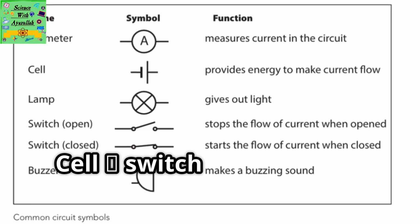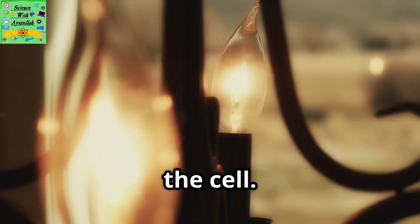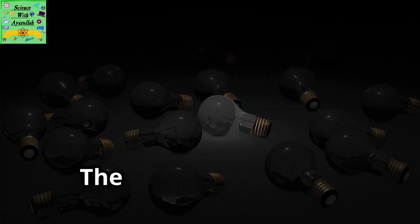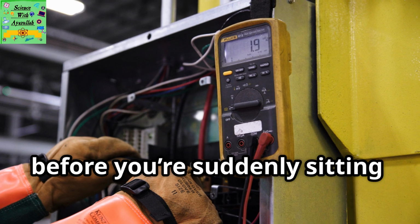Circuit 2, a lamp you can measure. Cell, switch, ammeter, lamp, back to the cell. The ammeter tells you the current. If the current drops over time, the cell's running low on stored energy. The lamp will dim too, but the meter gives you the early warning before you're suddenly sitting in the dark.